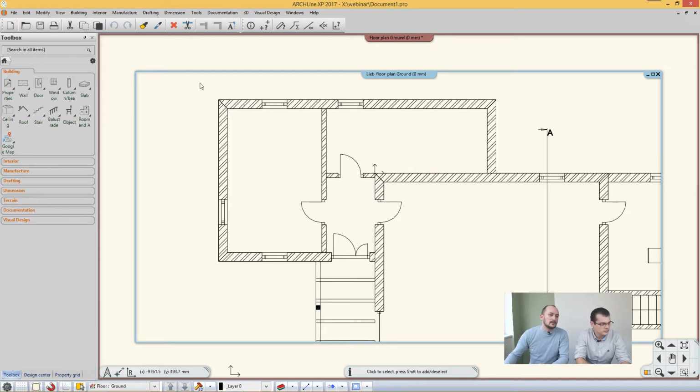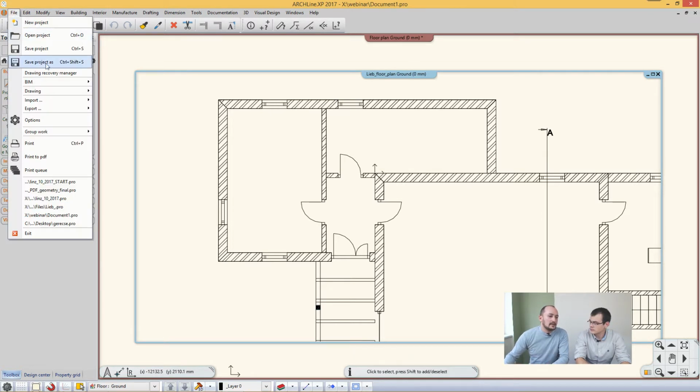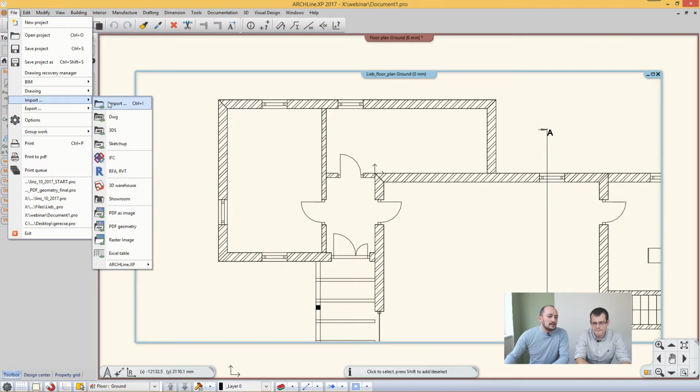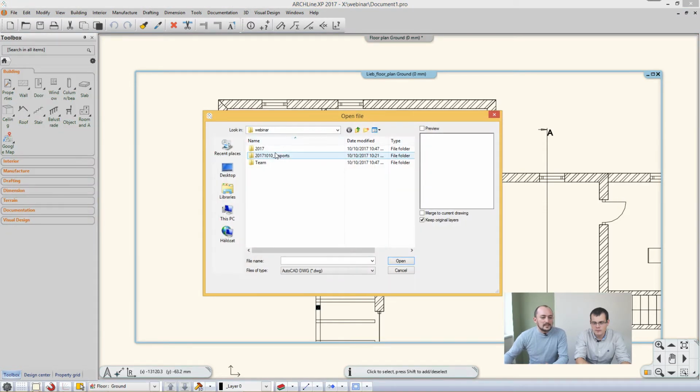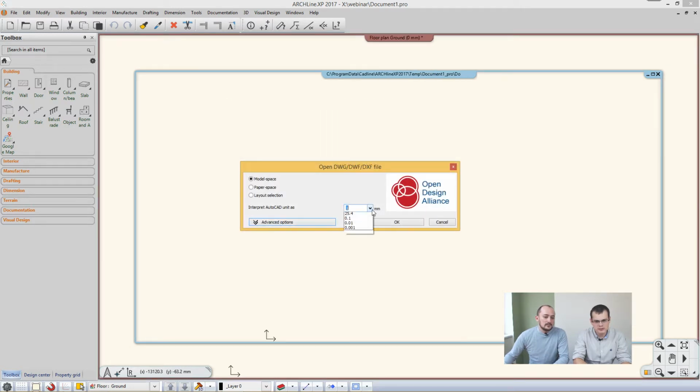And it's worth mentioning, I won't import it again. I'm just simply showing a very specific important value, which you should check if you are working with imperial units. If you select this value, this is the multiplier that you should use when you import from inches drawings which were created in imperial units, walls and anything else.